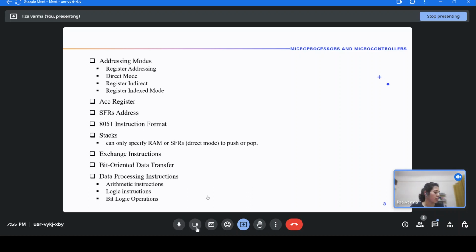Okay. So decimal adjust is the instruction used when you're doing your operations in your mind in decimal numbers, but the processor is taking them as hex numbers. After arithmetic operations, it will give you the answer in hex numbers.